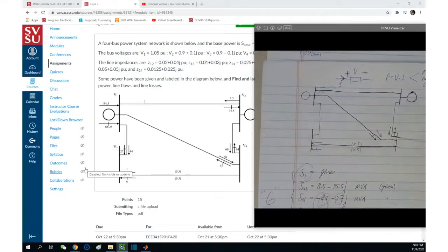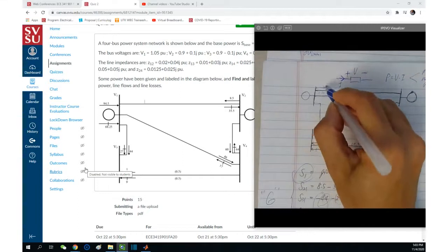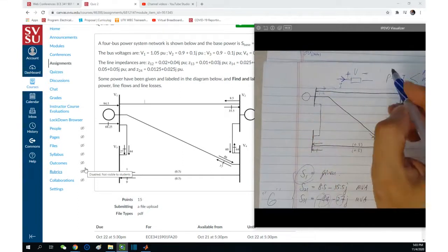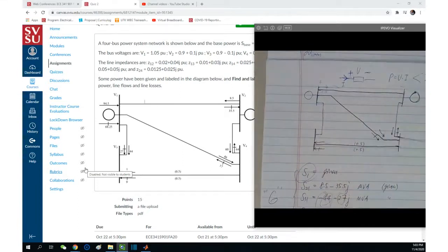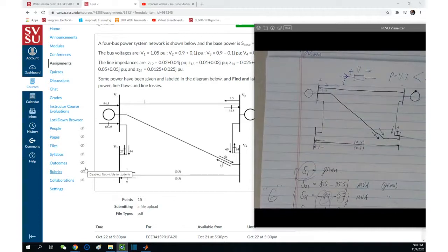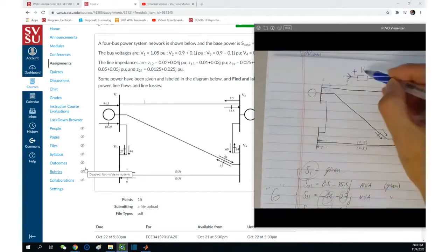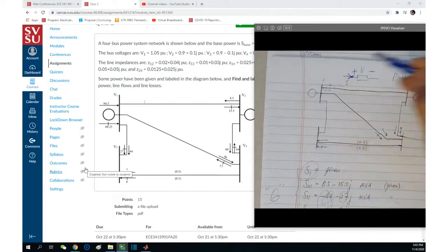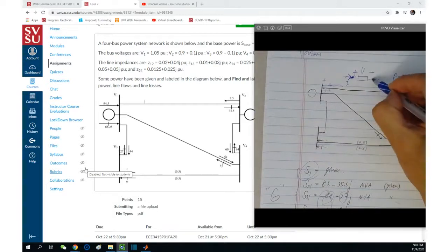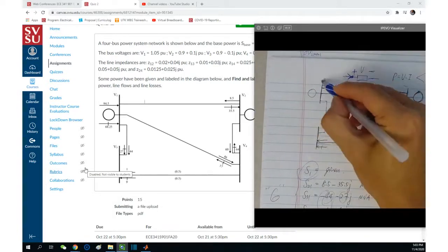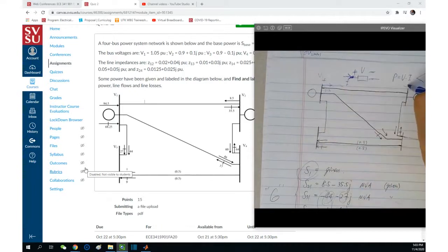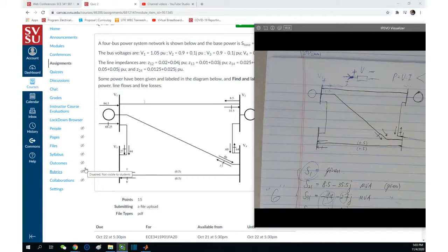And then you are following this direction current, you're following this polarity voltage. This is because this node represents this node, this node represents this node, right? So this is positive, this is negative. That's why you're using V1 minus V2. Yes, it's following the negative sign convention.